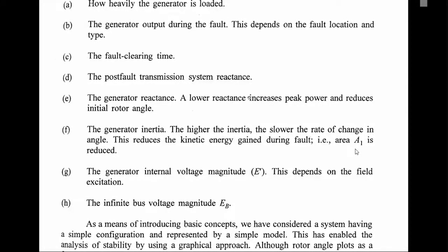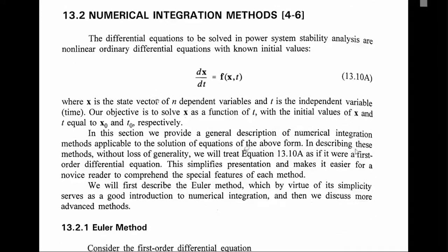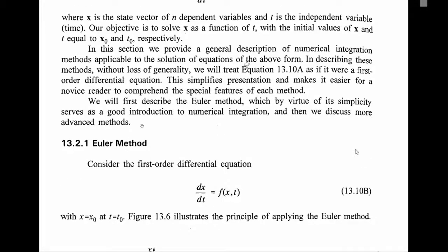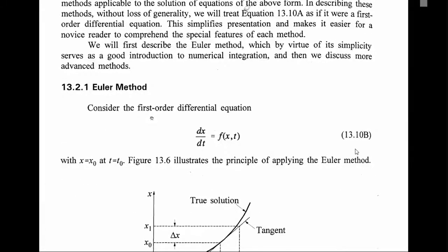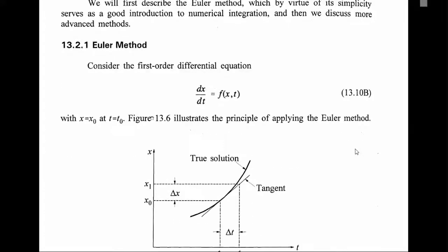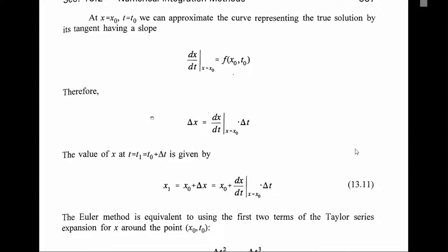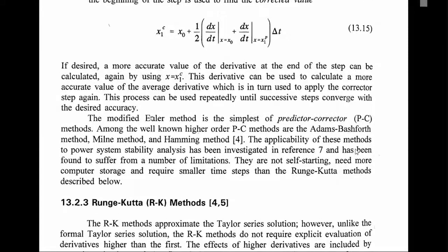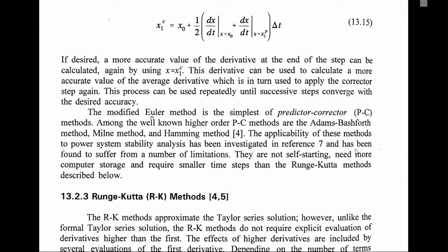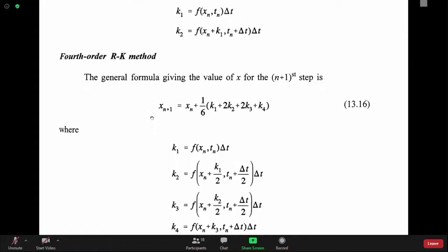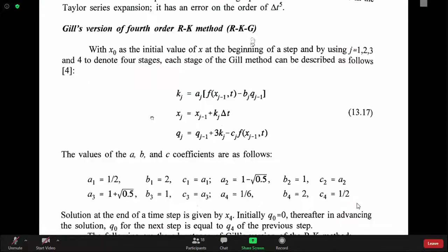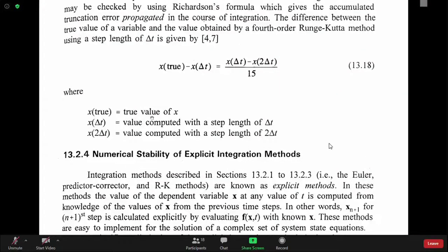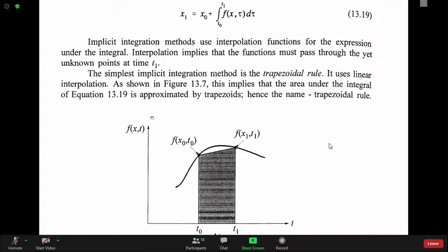So these are the numerical integration methods you have, such as Euler's method for finding a solution for an ordinary differential equation which is non-linear. You also have the modified Euler's method, and you also have the Runge-Kutta method. You have many methods, but you will see later how these methods are implemented in our simulation.